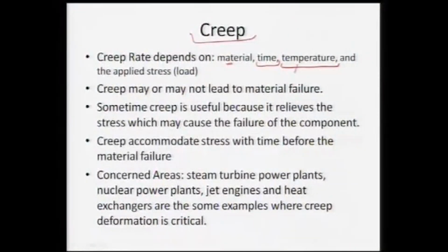Temperature, again if we keep the material at very high temperature, the creep rate will be very dramatic, very high, and the material will deform very rapidly. Applied stress, so again it also depends on the kind of loading that is being incurred on the material. So, if we have very high applied stress, the material will undergo a very high rate of creep. So, we can say the creep is dependent on many parameters such as material, its microstructure, the time of creep or time of exposure, temperature at which the creep is occurring, even the applied stress with which the loading is being provided to the material.